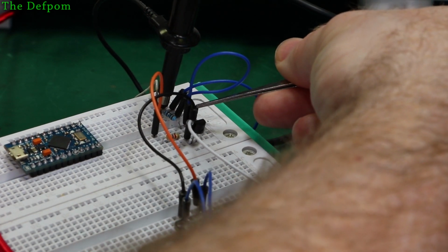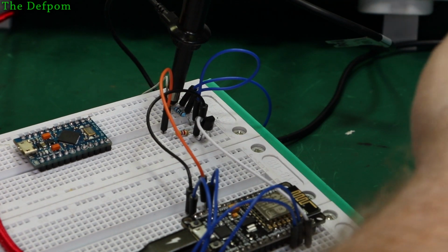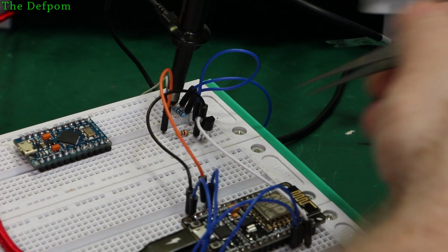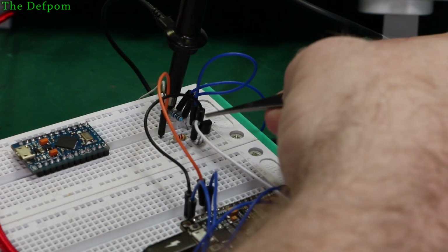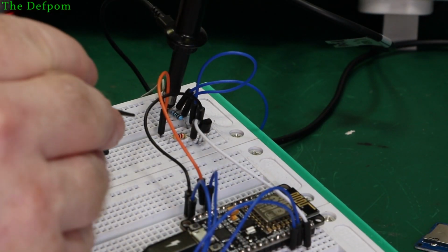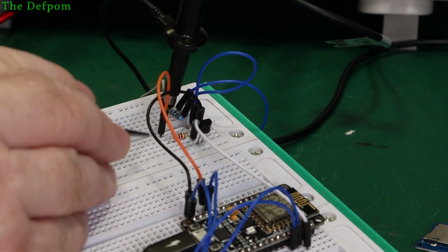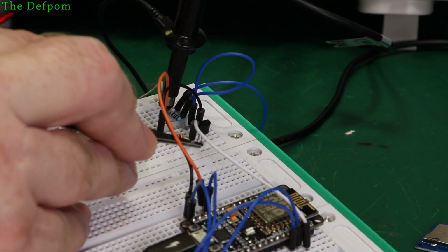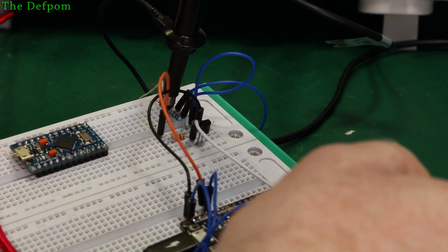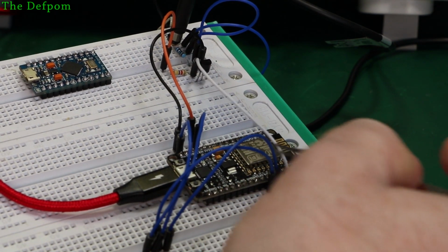So you've got the ground there, or 0 volt rail, going straight down to the ESP8266 or Arduino, whichever one you're using. Then obviously to the emitter of the transistor. The pin out is emitter, base, collector. Now that's that part of it. The pull up side is done from the 3.3 volt rail in this case, from here through this resistor to the collector of that transistor, which then also comes out to the RX line of the ESP8266 down here. So that's the actual serial connection through this wire.